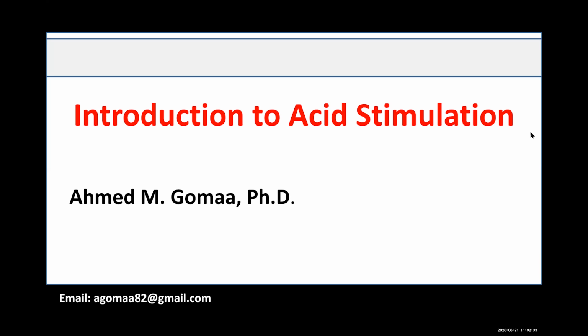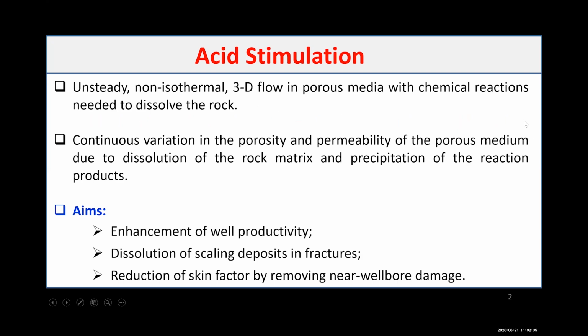Let me start with a simple definition of what acid stimulation is. Just to highlight, it is an unsteady type of injection. So it's not steady state, it's actually unsteady state. It's non-isothermal, so temperature will change as you are injecting your fluid, as the fluid is reacting. And it is also a 3D type of flow. It's not linear flow, it's not radial flow. If you have a perforation, we are talking about spherical flow. So we have a flow in a 3D pattern.